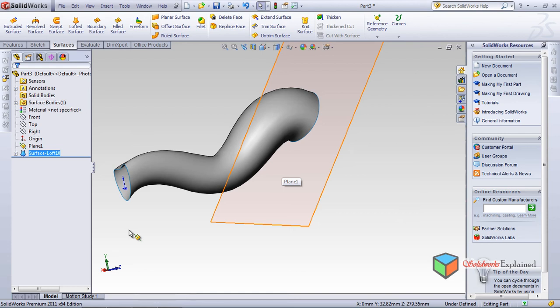Now again, the sweep and the centerline parameter, what is the difference? The first difference is that in sweep you touch the edges with the guide curve, it touches on the sides, but here you can also touch on the center. For example, let us assume there is an imaginary curve passing through the center, so both the sides almost remain the same.